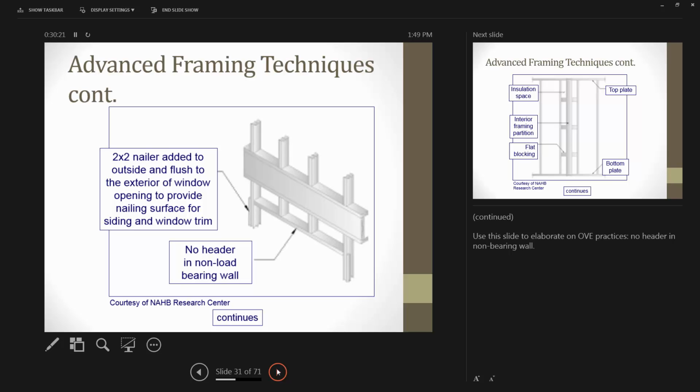concept, but as it turns out, it actually saves money by putting more insulation in the wall, and it's far more effective as an energy efficiency measure than as a lumber saving measure. They used to do 12 by 12, we went to 16 by 16 with proper lumber adjustments, with the 2 by 4s, 2 by 6, 16-inch on center, and the study says it saves 40% on energy.